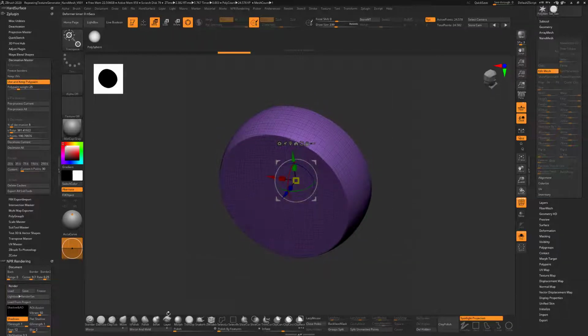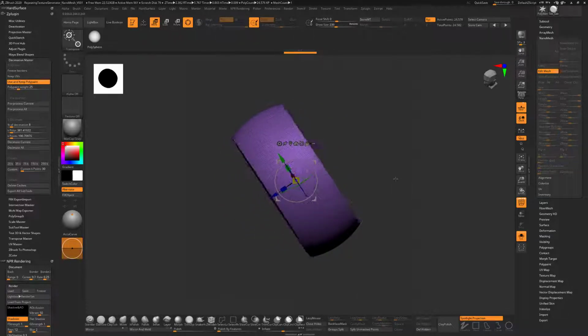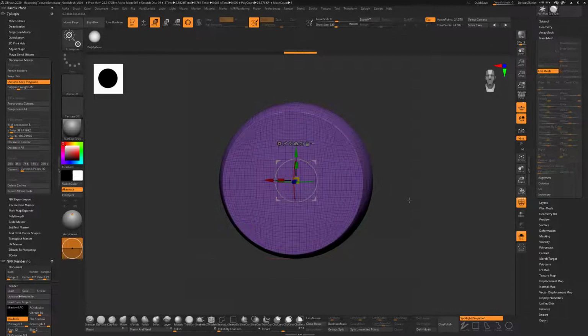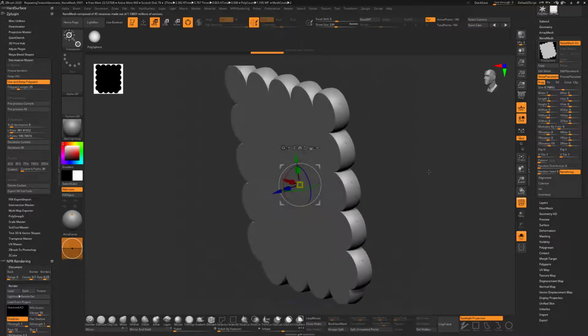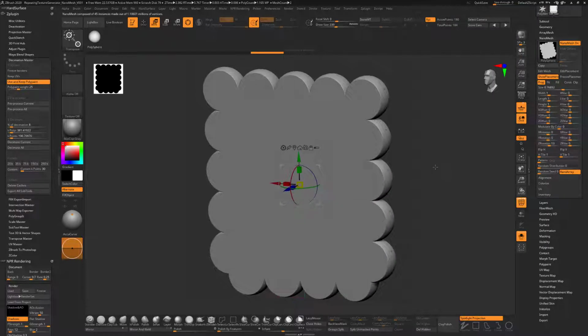Now I've got it set up on my interface. We've got a mirror and weld, and I can mirror and weld across the x-axis, but I could also mirror and weld across the z-axis and make sure my model's the same on the front versus the back. And when we're done with these changes, we just click off of Edit Mesh, and it'll put us back into that mode, and we've manipulated the objects at that point.